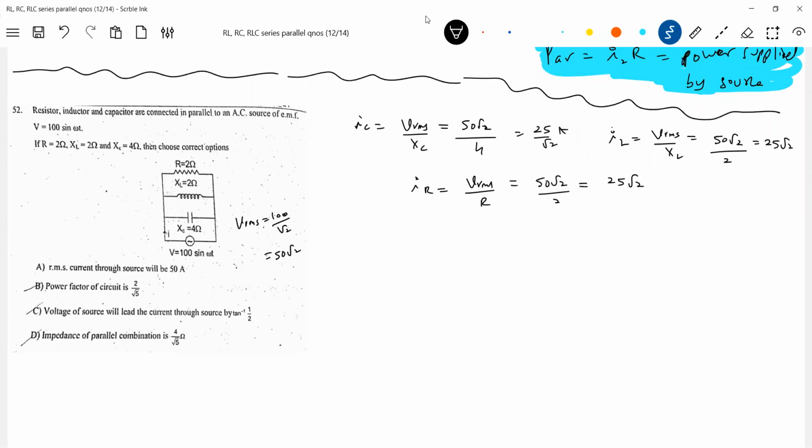Let's directly get into the vector diagram, or what you can call the phasor diagram. Applied voltage VRMS, I'll take it as reference, 0 phase. So we know current IR should be in this direction. And across the inductor, current lags the voltage, IL. Okay, we have this much here. So get the resultant current.